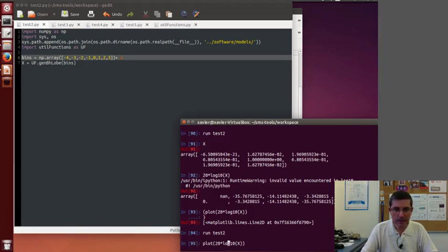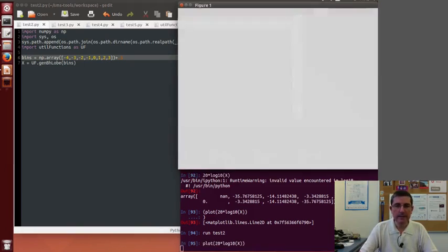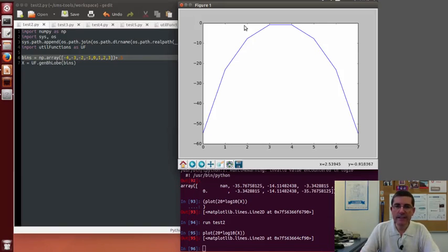Okay, now we see that these are different samples. There are no center samples, so the peak is basically in between 2 samples. This is how we generate main lobes corresponding to different frequencies, because we are moving this main lobe around these samples.